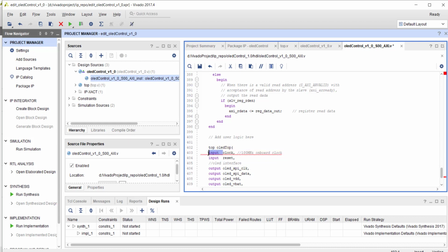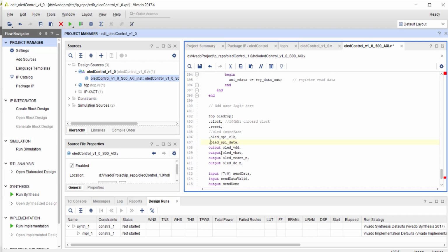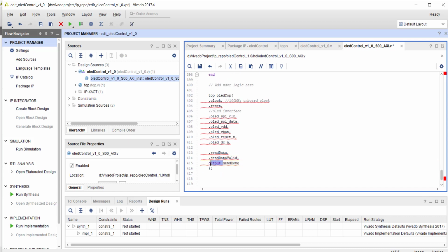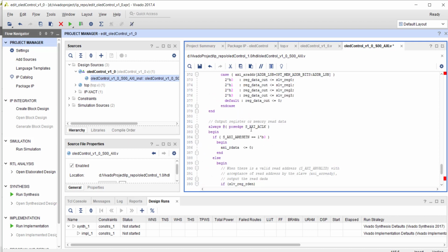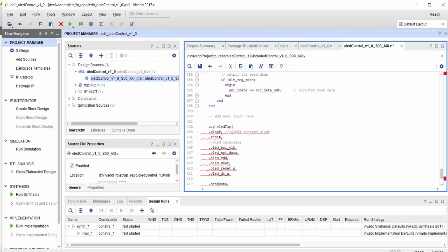Now we are going to connect the signals. Remember, previously the clock and reset were directly connected from the input output pins of the FPGA, but now that is not the case. This code is inside an IP, so this clock should be the XC clock coming to your IP. So I will take the XC clock, this one, and directly connect it to the clock signal here.